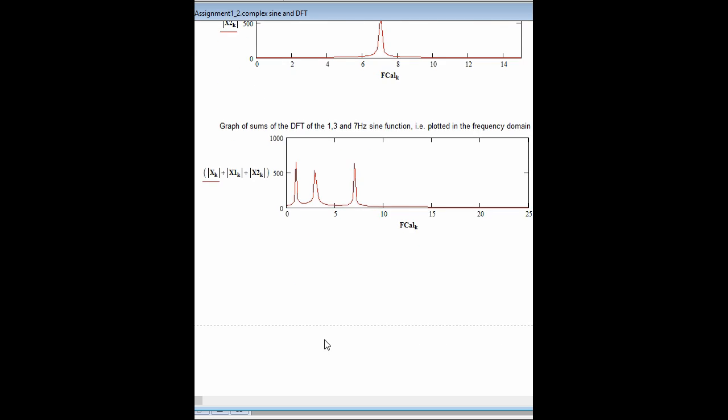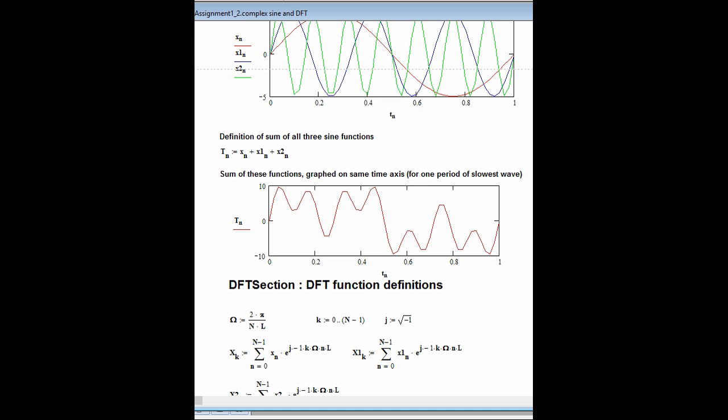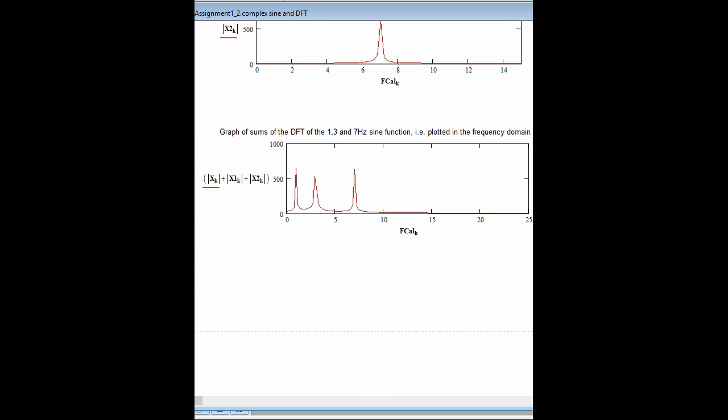You can Google fast Fourier transform. It converts the 3 sine waves added together and gives you 3 peaks, and these 3 peaks tell you what the 3 frequencies are. If you only want one of them, you can design a low pass filter, a band pass filter, or a high pass filter that will only let that frequency through.